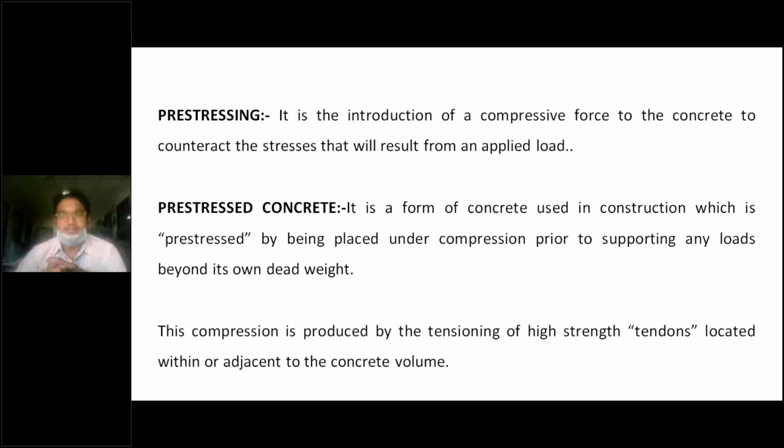So here it is the introduction of compressive force to the concrete to counteract the stresses that will result from the applied force. What do you mean by prestressed concrete? It is also a form of concrete used in construction with the help of this prestressing technology, whereby it is placed under compression prior to supporting any loads beyond its dead weight. That is exactly prestressed concrete. The compression is produced in the concrete with the help of the tensioning of high strength tendons.